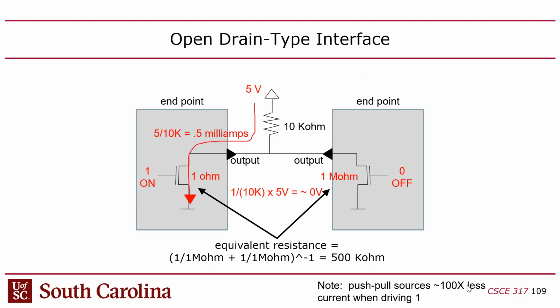Open drain is where basically the bus, the shared wire, can have multiple peripherals on that wire, and there's a pull-up resistor. So if no one's actively pulling down, it's logic high. You guys with me? Unlike these LEDs, these are not open drain. These LEDs are connected to push-pull drivers, and because I'm not push-pulling them, they're dead. There's no pull-up resistor there. Well, actually in that case it would have to be opposite because they already have a pull-up on one side. But the point is that if no one's doing anything, it looks like a 1, right?